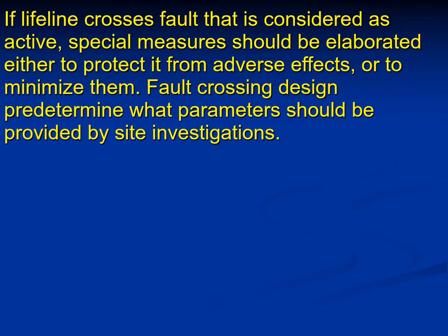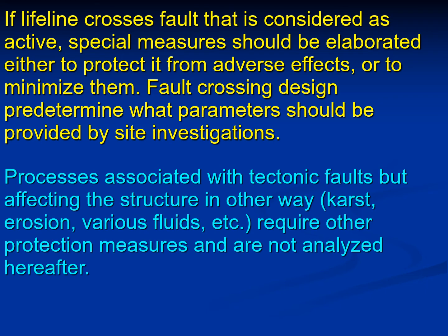If a lifeline crosses a fault that is considered as active, then special measures should be elaborated, either to protect it from adverse effects or to minimize them at least. Fault crossing design predetermines what parameters should be provided by site investigations.